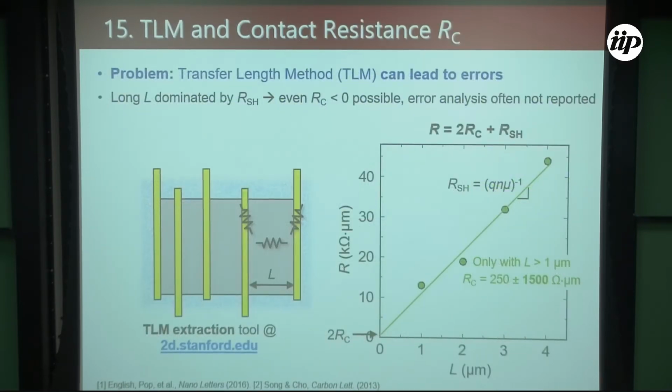Okay. Now we're coming to probably one of my favorite topics, contact resistance measurements. I'm obsessed with contact resistance measurements because we make all these transistors that I showed you earlier that are sub 100 nanometers. And if a transistor is less than 100 nanometers, it's almost all contacts. The mobility almost doesn't matter, actually. I mean, it should be pretty good, but the contacts are dominating.